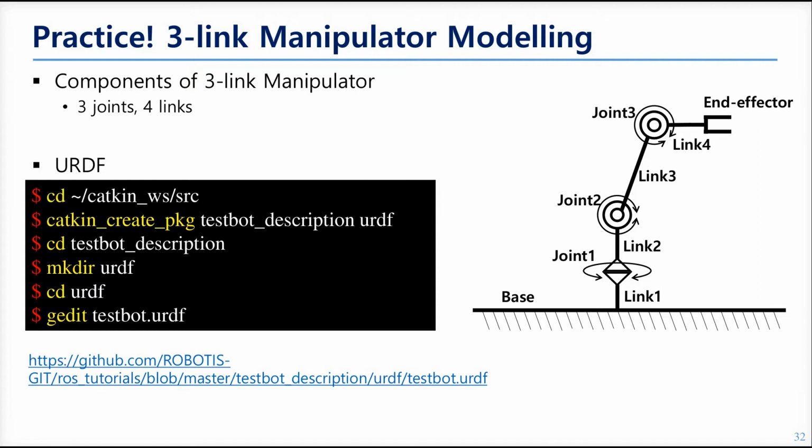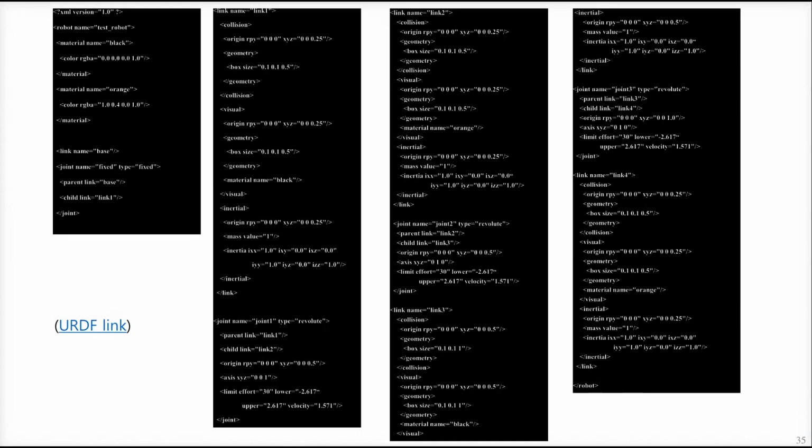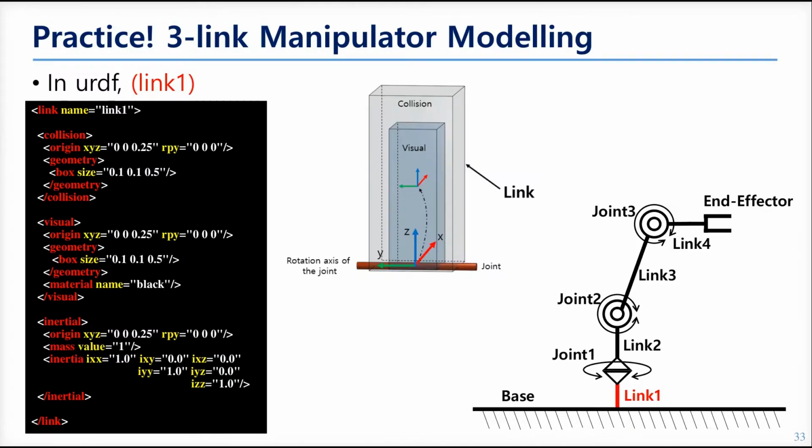Make a package and a URDF file inside the package. We will put the sources in so that this can visualize the manipulator. And this is the code you should put in the URDF file. And from now, we'll see the details of each line. Let's see from the first link.